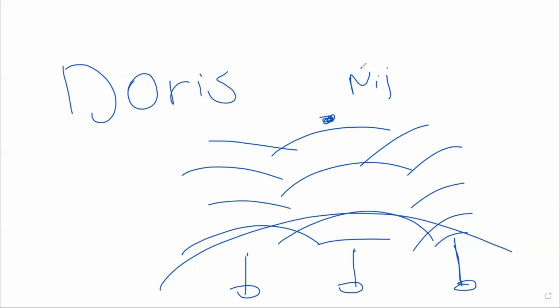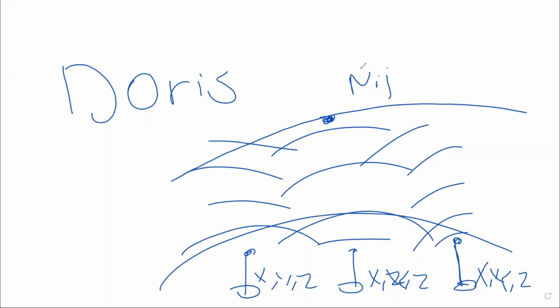In this case, the positions of these beacons or stations are known with high accuracy, and the Doppler count points can be regarded as known points, and the coordinates of the satellite and the orbit are unknown.